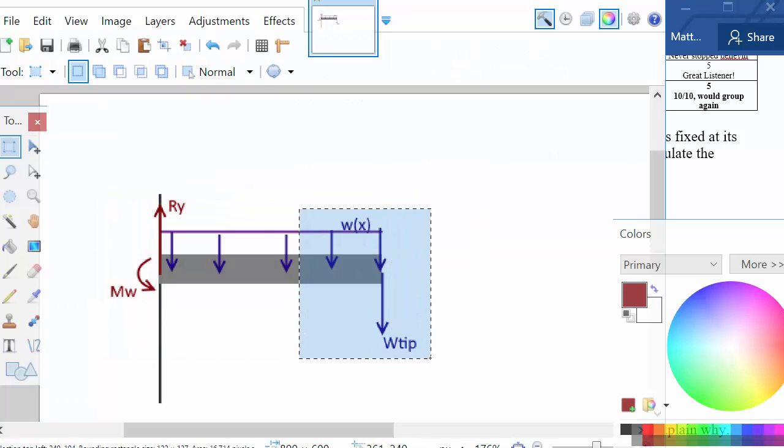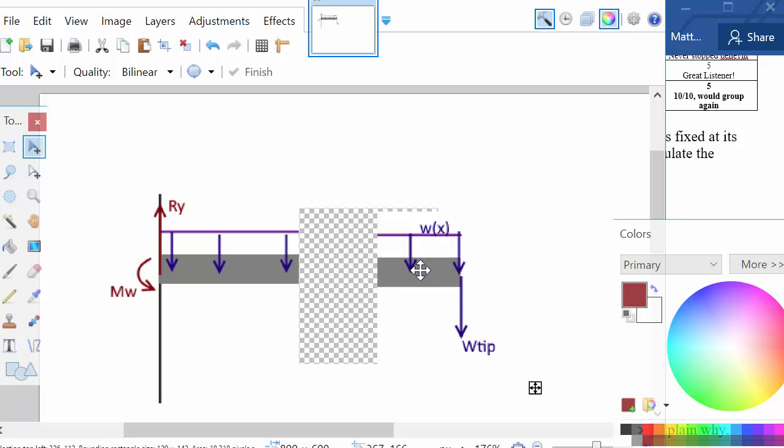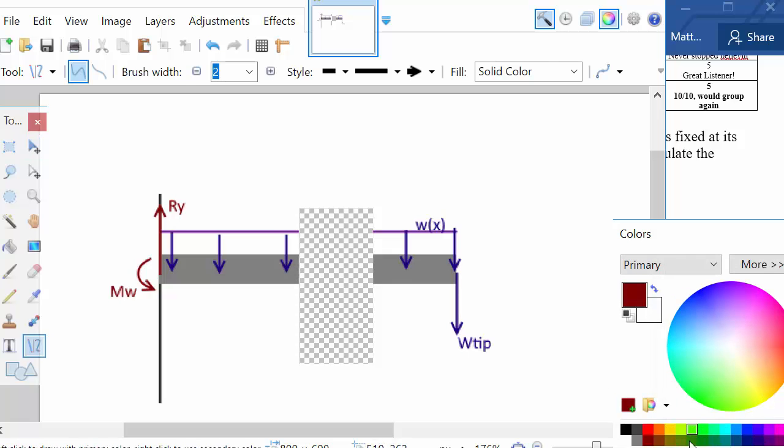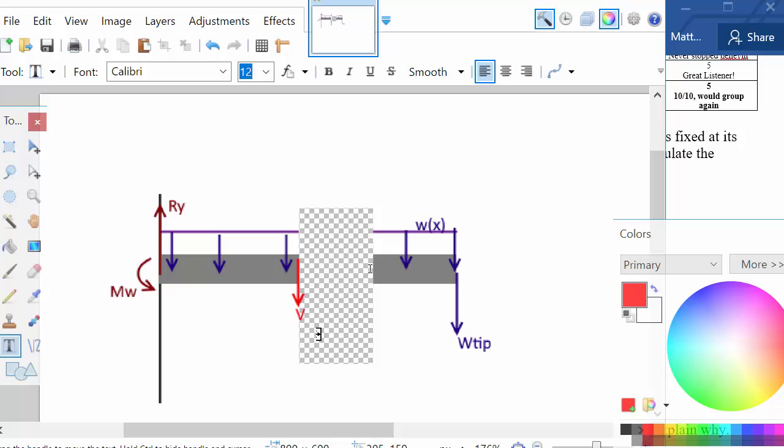So the point of the internal shear force and bending moment is so that at any point you say, hang on a sec, this thing has to be in equilibrium on each side. So that means that we must have some internal force set up. So maybe we'll take red here and use that for the internal shear force. And our regular sign convention for the shear force, I believe, is that V points like that, and then it's equal and opposite on the other side. So this is representing the force that this right side must be putting on the left, and the Newton's third law pair, which is the force that the left side of this beam must be putting on the right at any junction. So V is going to be a function of X, of where along this beam we are.